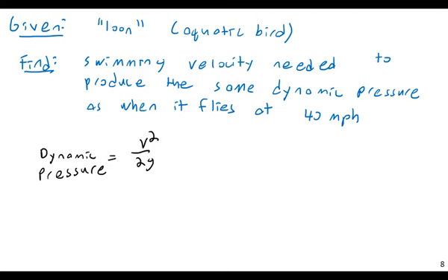Basically, when I talk about dynamic pressure, what I am saying is, what pressure is this equivalent to? In other words, the energy represented by this velocity of a fluid, what pressure would it take to have that same kind of energy? I'm looking at equivalence, okay? Or another way to look at this is 1/2 rho v squared, as we'll see when we work with drag later in the semester.